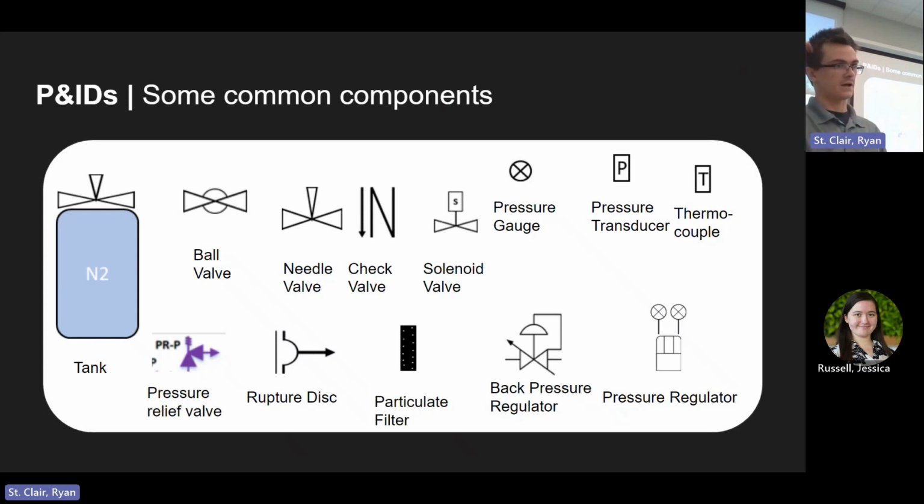And again, these are hand valves, but they can also be what are called pneumatic ball valves. So you can have a line of pressurant going to a ball valve and use that pressurant to turn on a ball valve remotely instead of having that be a hand or a manual process. So then next we've got a needle valve.